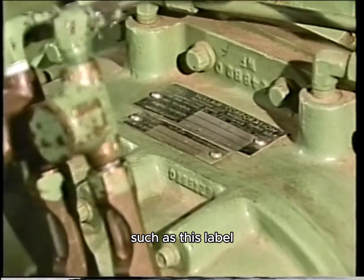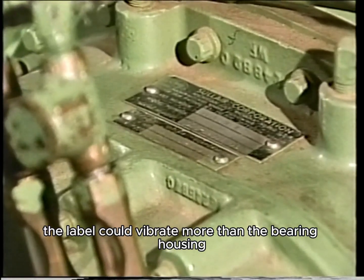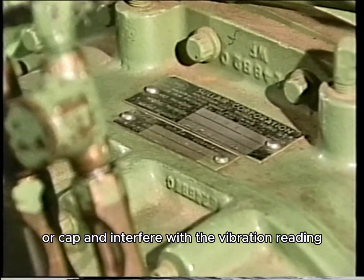The pickup should not be mounted on an unstable surface, such as this label. The label could vibrate more than the bearing housing or cap and interfere with the vibration reading.